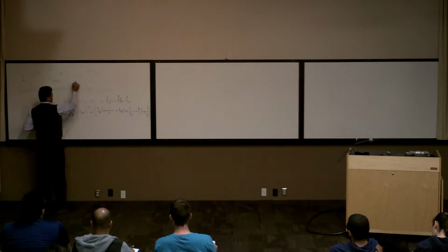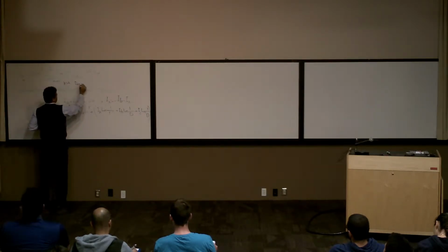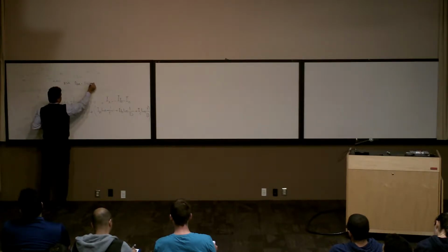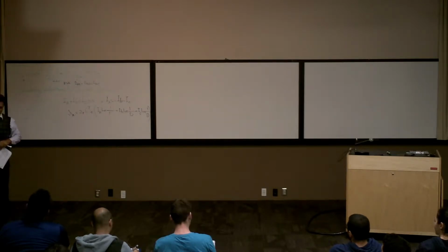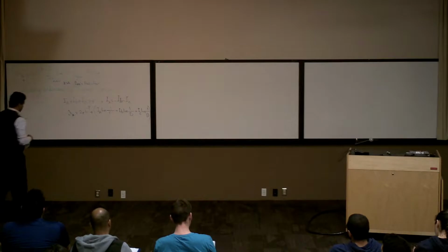So you have three. DAA, K is A, right? M is going to be A, B, C. It's going to be DAA, DAB, and DAC. DAA is the distance of the conductor A to itself. How much was it? R prime. We call it R prime.